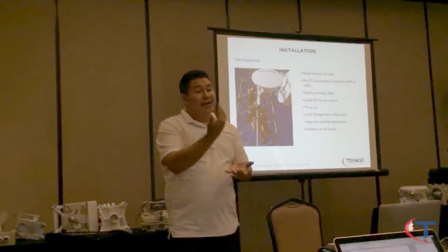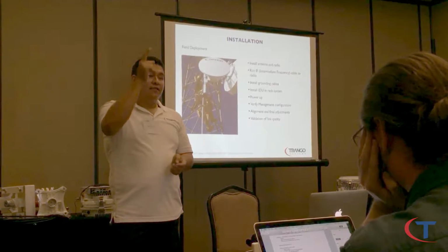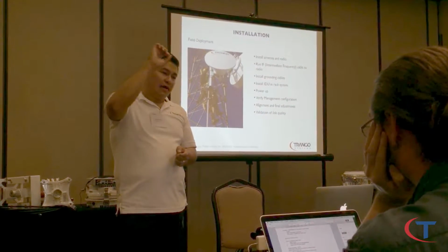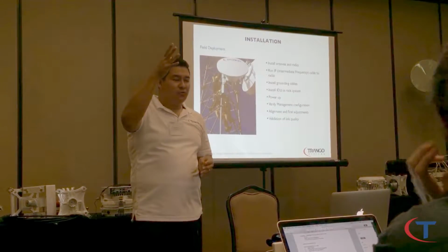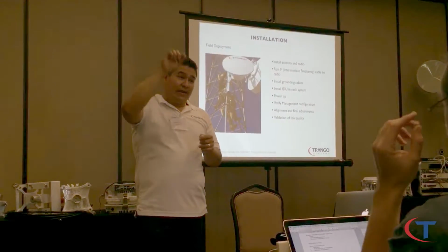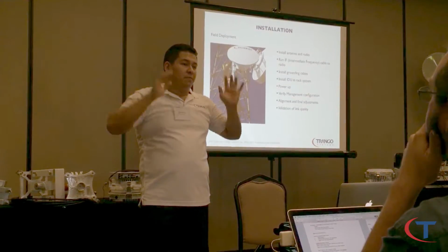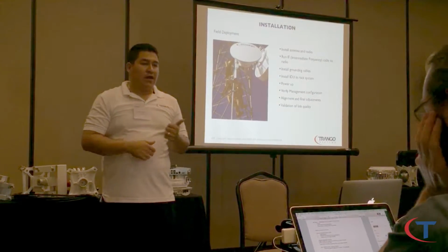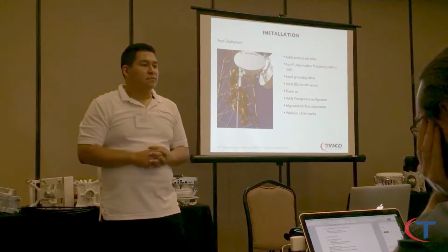And then there's another extra feature there, a polyphaser. So a polyphaser is the inline protection from the ODU to the IF cable. So if it gets hit by any reason, by lightning, instead of coming down, it's a gas tube that's going to blow and it's going to stop it. So grounding the ODU, and a polyphaser. That's what you better want. Okay? A polyphaser is designed strictly for lightning strikes.